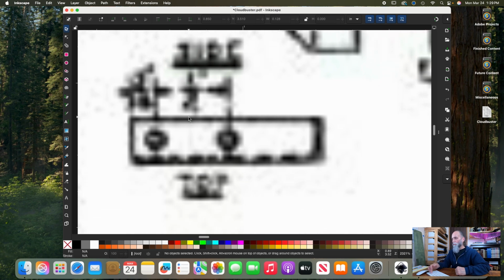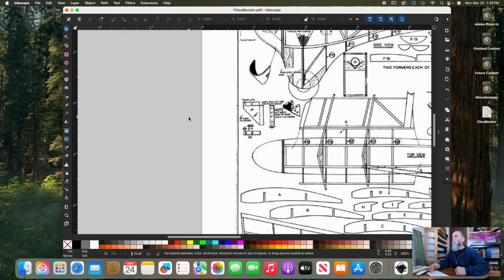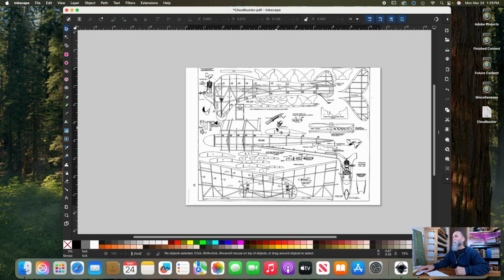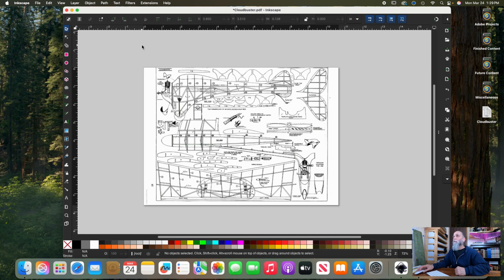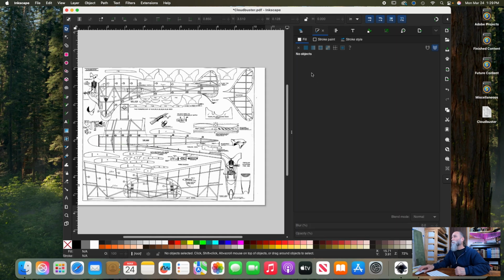So to zoom out, minus sign. Okay, I'm zooming out just so I can see it. And now I'm going to go up to, where am I going? Nope, not going up, going to the side. Click those 3 dots. So in here, you're going to see there's a scale, transform tool. That's where the scale option is. So there's the scale. And so right now it's set to, you can change it to inches or millimeters. We're scaling in percentages. So it's already at 100%.